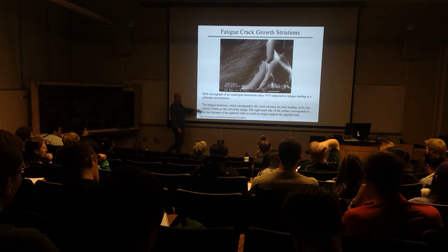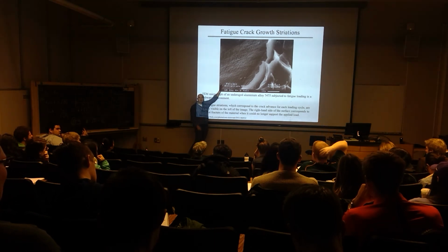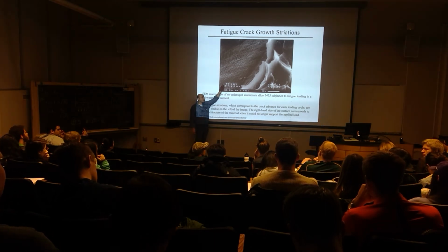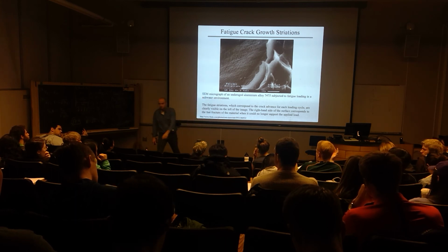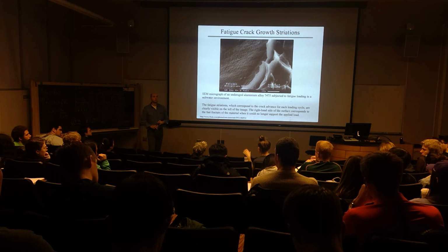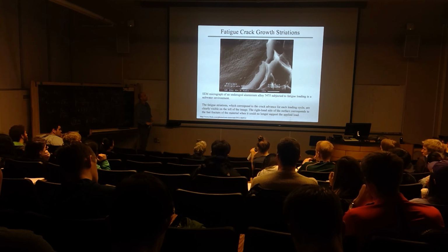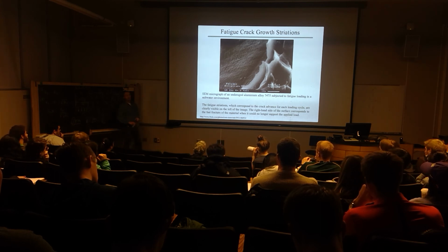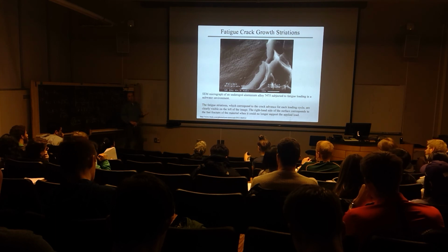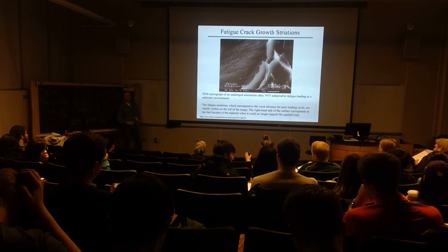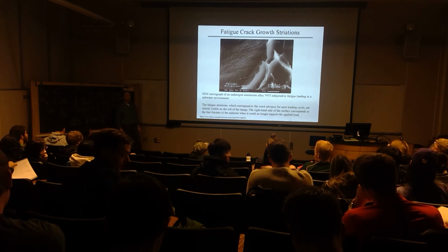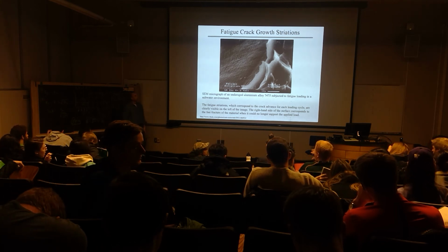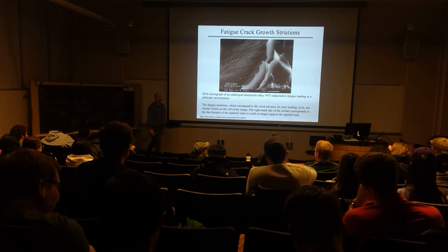So we always look for fatigue striations in thinking that fatigue crack growth might be a contributor. So if you're running a fatigue test that has 200,000 cycles, are there going to be 200,000 striations? They might not all be evident, and most likely, I don't know that anybody's ever counted that far because we have to do that in SEM. So there's probably better things to do. But normally there should be one for every load. There'll be one for every load. So we'll talk about this more